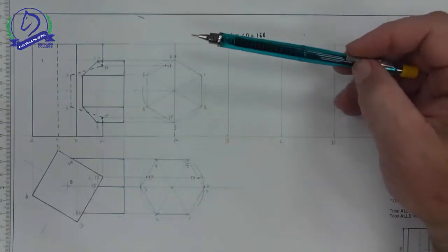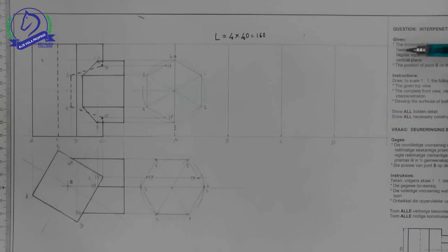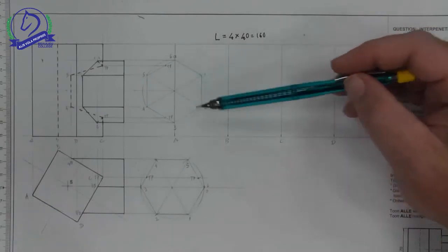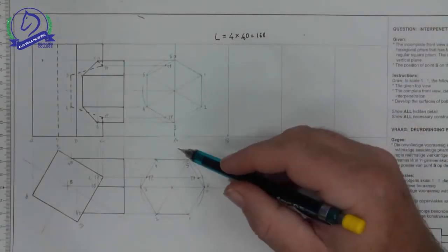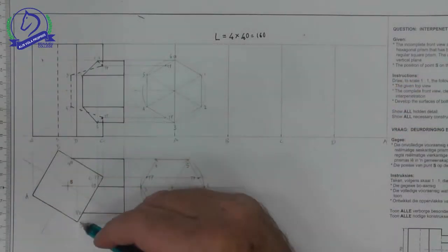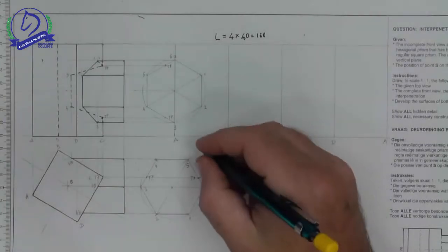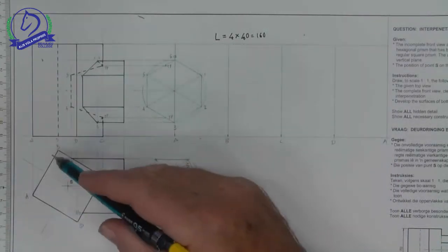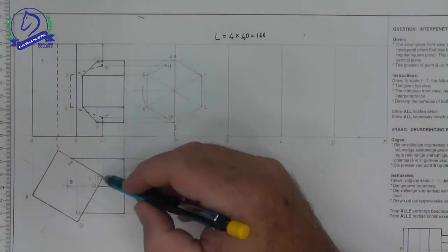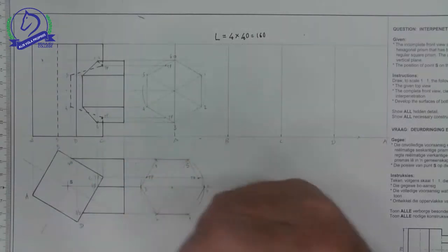I've projected my height measurements across. Then I've marked off the length of the sides of 40 millimeters each. It's just interfering slightly here with part of that. I want to raise that. And I've labeled them corners A, B, C, D, and back to A, relating to the labeling that I've done here. So what I need to remember is that between A and B, there is nothing that needs to be developed, and between D and A, also nothing. The whole hole for this curve of interpenetration is between B, C, and D.